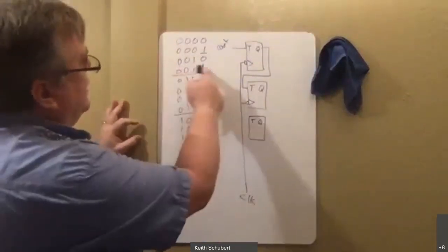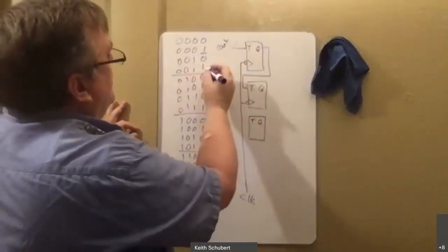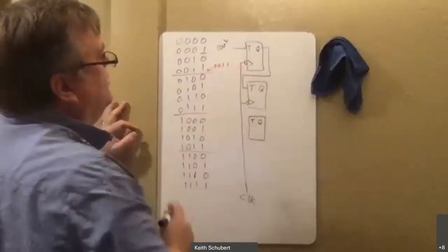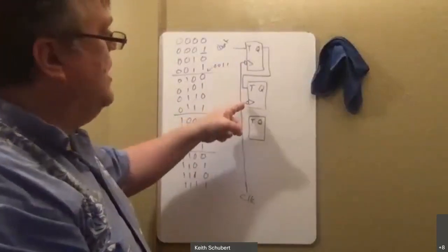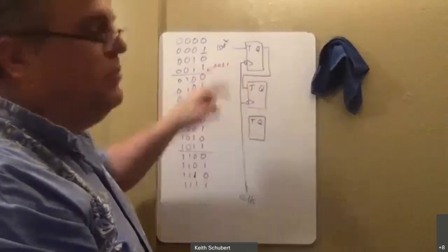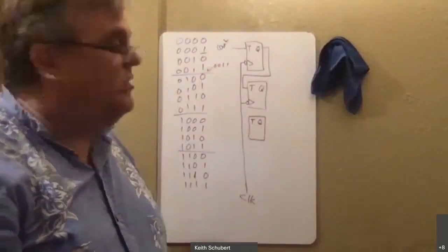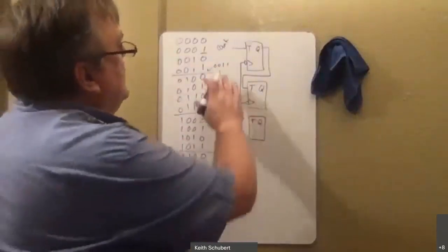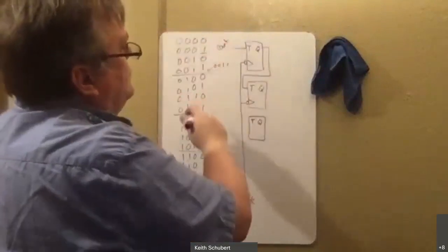What if at this time period, when I get right here, what if count turned off so that there's a whole bunch of 0011s that are supposed to stay in here? Well, the clock pulses are still coming, and it's going to see that one there, so this one will be toggling like crazy. So while this will do the transition as long as everything's going fast, it won't handle in between delays.